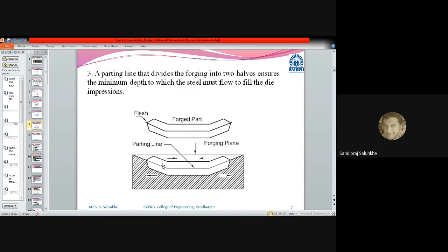So while this material flows, because you know that in case of forging, what we are going to do is heat that component job at a certain temperature, near about 720 degrees Celsius, which is the recrystallization temperature of that ferrous material. I'm not sure about it. I'm not exactly telling you what the temperature will be, you can find it in a metallurgy book, but that temperature is near about 720 degrees Celsius, where that part will get heated as red hot, and then